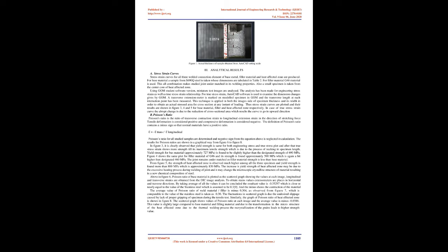The red dot in Figure 7 shows poor quality as a stochastic pattern. In some samples the surface components created in the software disappear after just 100 to 150 images. Depending upon the quality of the pattern, the results of DIC analysis vary in accuracy, and problems can be observed in plastic areas when the pattern is highly distorted, as shown in Figure 1.